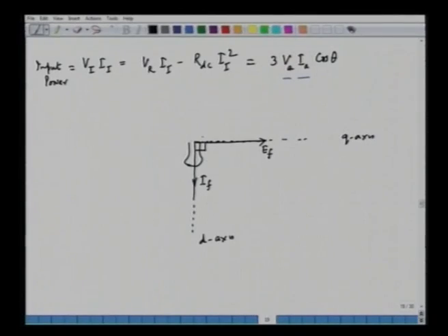Then we have the current, and the current can be in any arbitrary direction based on the power factor. So let us say that this is the current, armature current IA. If this is the armature current, we know that in case of a motor, we can write down this equation, that the applied voltage V is equal to EF plus J IA XS plus IA RA.